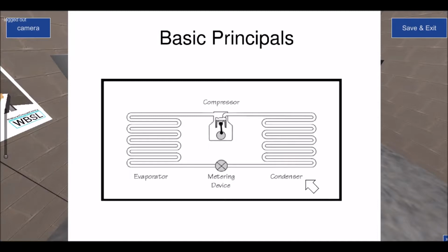When we're looking at refrigeration systems, your refrigerated cabinets, your beer coolers, any commercial refrigeration system, even water chillers, effectively what we're trying to do is absorb heat from one area and dump the heat in another area. The evaporator is the heat exchanger that absorbs the heat, and the condenser is the heat exchanger that rejects the heat.